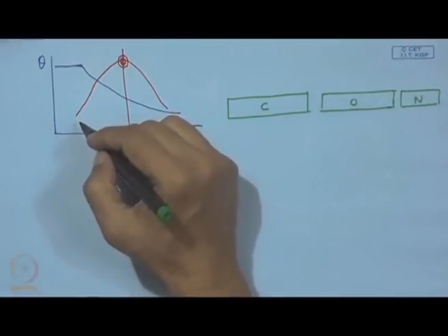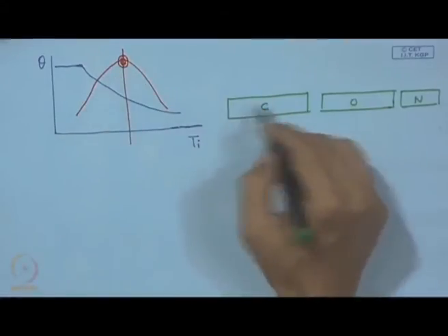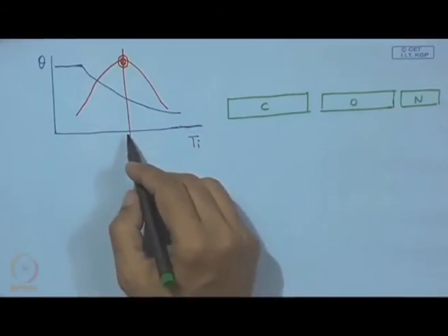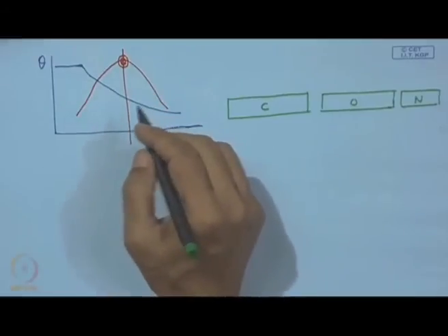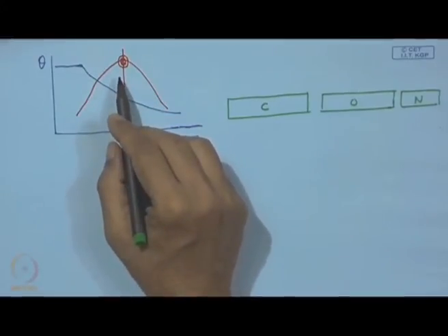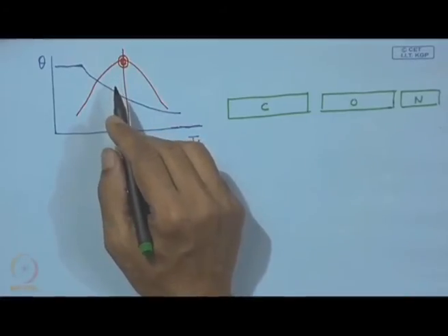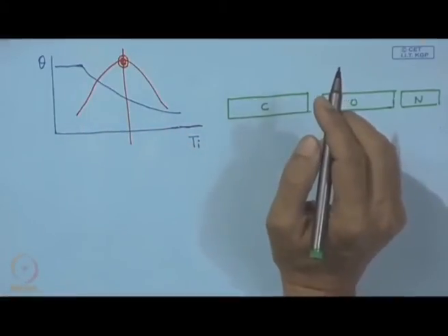Unless we have a certain quantity of titanium, this is not going to happen, and with a certain percentage one attains the very peak of adhesion strength, and this we can call work of adhesion, that means energy required per unit area to separate this interface into two surfaces.